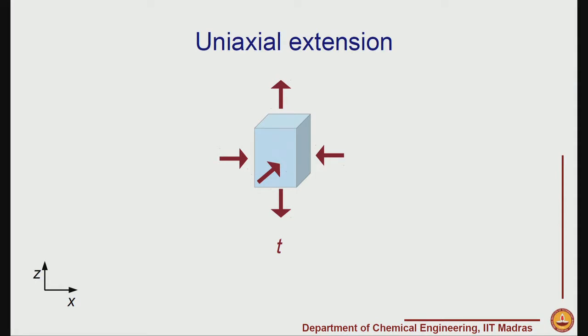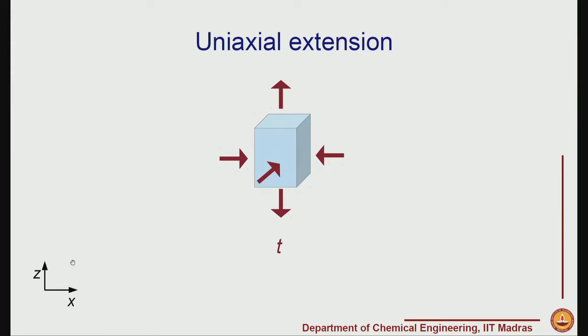For uniaxial extension we will use a rectangular coordinate system. Again, this is something more difficult to achieve in a lab setting. A rectangular block of liquid is difficult to achieve. In case of solids we can of course cast it into a solid bar of square cross section, and then do the testing. In fact, in most dog bone testing, the cross sectional area is rectangular. So, in case of solids this is quite usual, but just for understanding, in the classroom setting we might use